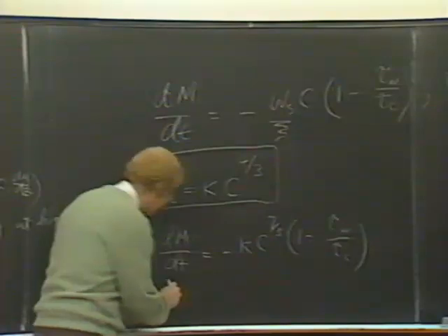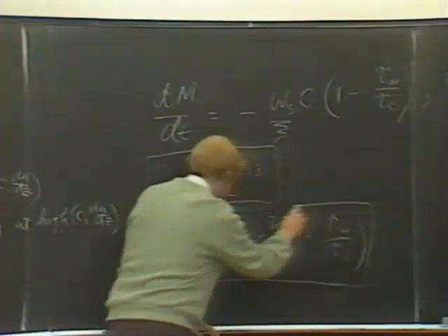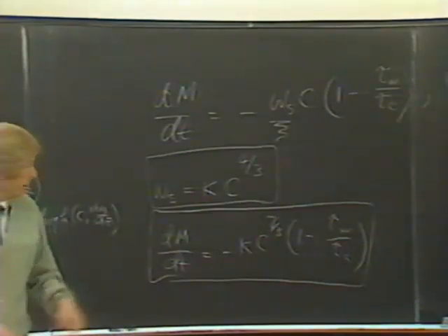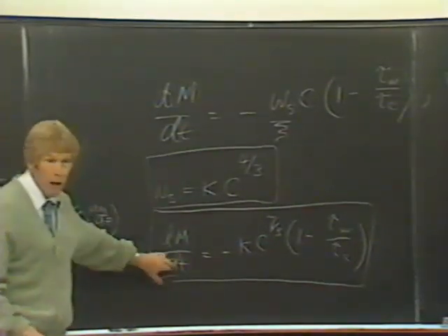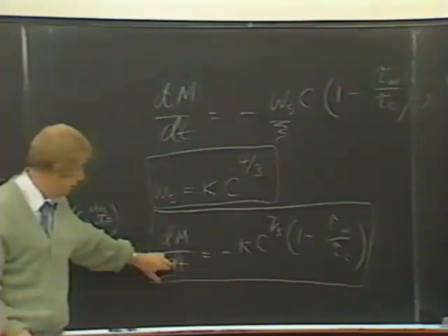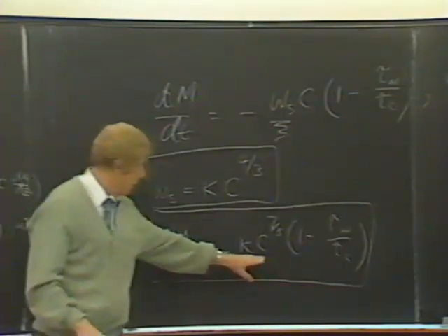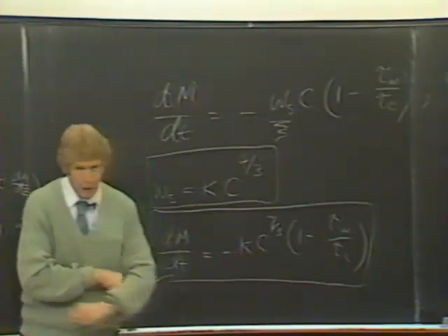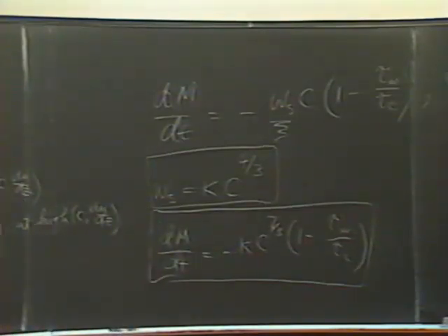What is G? G is the average velocity gradient in the flow, and he chose that to be equal to the power dissipation rate per unit volume divided by the viscosity, to the 1/2 power.